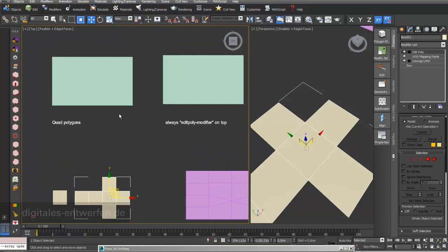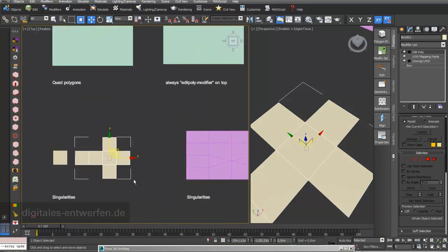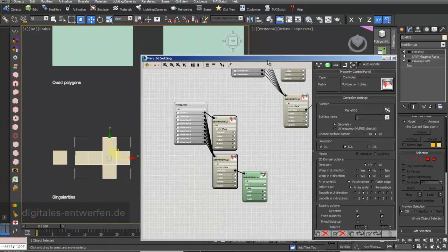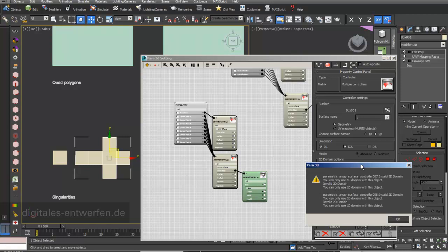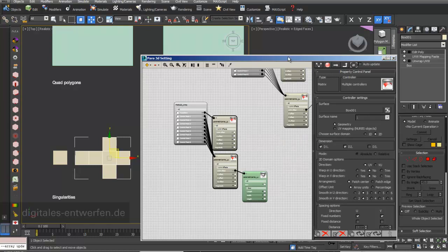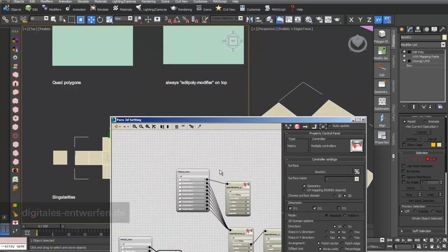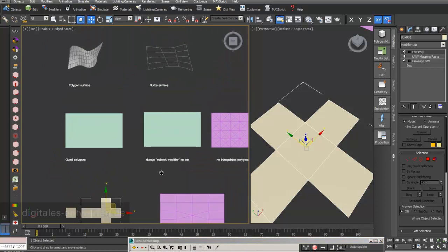It's a little bit like looking at the map, that there's continuity in your whole geometry, and then you can use a 2-dimensional surface. With this example, you can't do it. If I just choose it and I go into auto update, it just gives me an error that this kind of geometry I can't use. But I can use it with a 1-dimensional array, just because I have polygons, and each polygon only has 4 edges. So for a 1-dimensional array, it actually works.